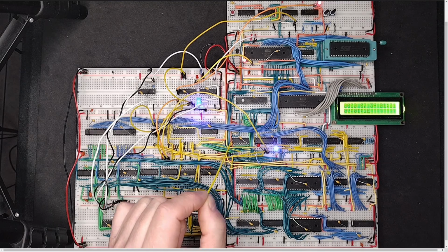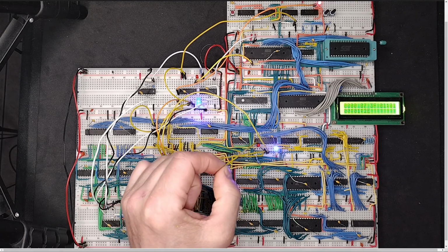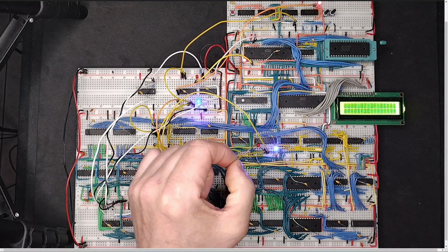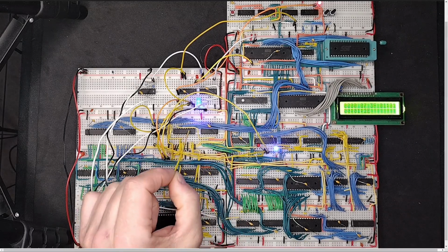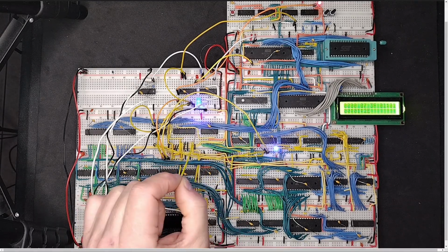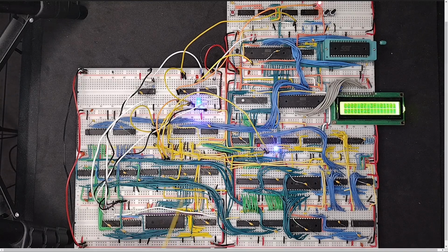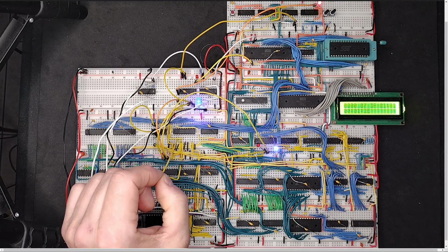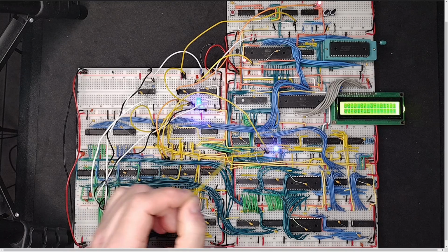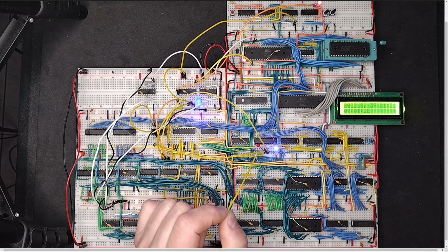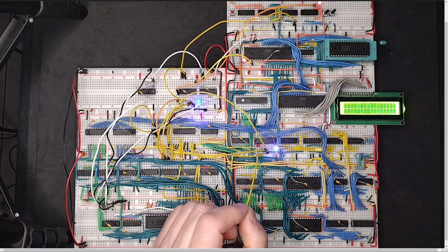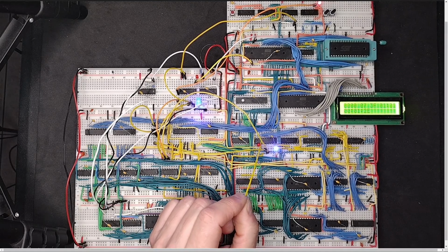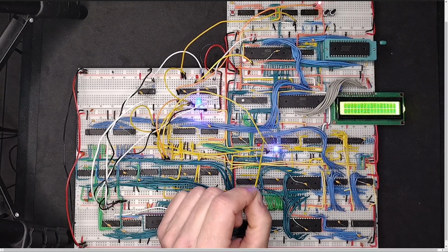And by doing that, I can write to this. This is a D latch. I can write to this D latch using address 5070, and I could read from this transceiver using address 5070, and they don't conflict with each other. So anyway, I've got this wired up so that it goes to data line 3, which is the same data line that I used to deactivate it. So data line on this D flip flop creates a register for writing to at address 5070.